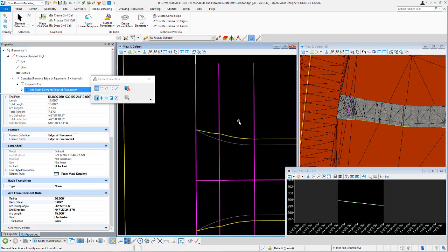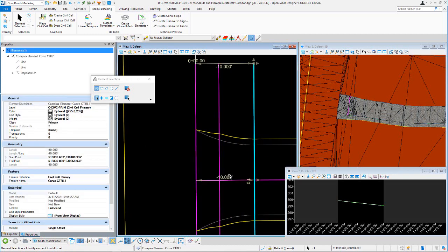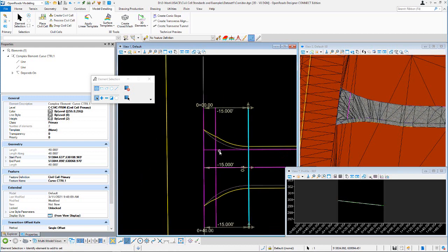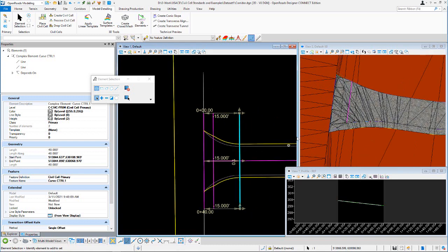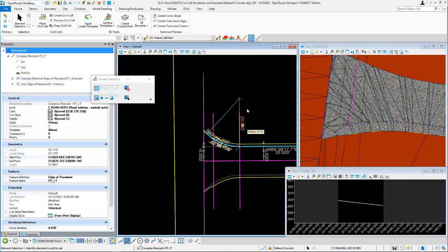So obviously you can change any of that. You can also change this, right? So if you want to back this up a little bit, if we want to make that negative 15, you can see what that's going to do is move where that arc starts back. Now, obviously there would be some type of limit there, I would think. Eventually you go far enough back, a 20-foot radius is not going to really intersect this right here. So there would be some limitations there, but that's how you can control where those arcs start, and also how to control the radius values and all that there.